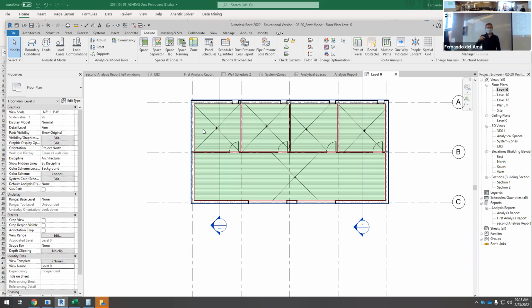And don't be shy, just multiply by 1.5. Okay, so we are architects, we are not engineers. Buildings don't fly. If you talk with aerospace engineers, they have to put rockets in the moon. Okay, so you cannot say, okay, double it. We are architects, we can say that. Okay, so if our boiler is 2000, or if our result is 2540 BTU hours, then we have to select a commercial boiler.